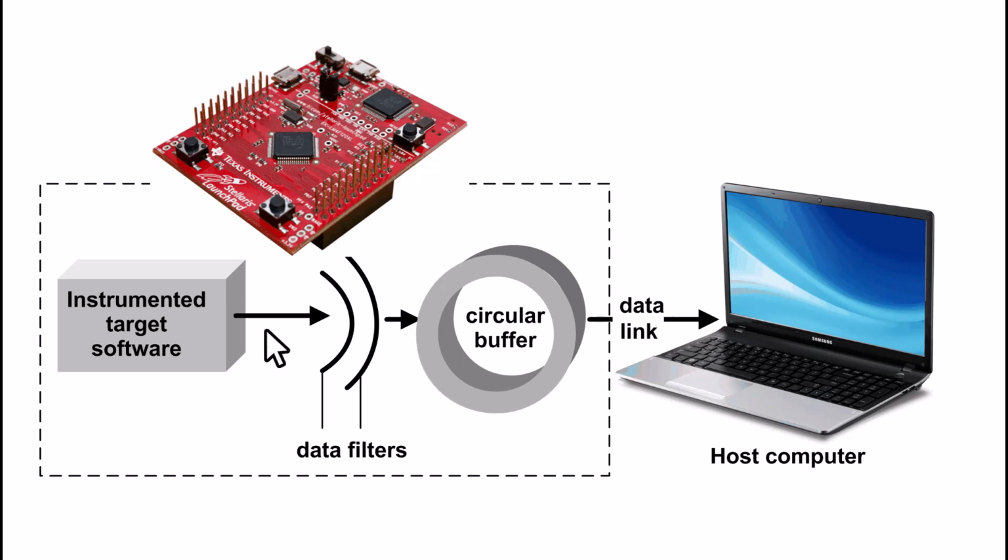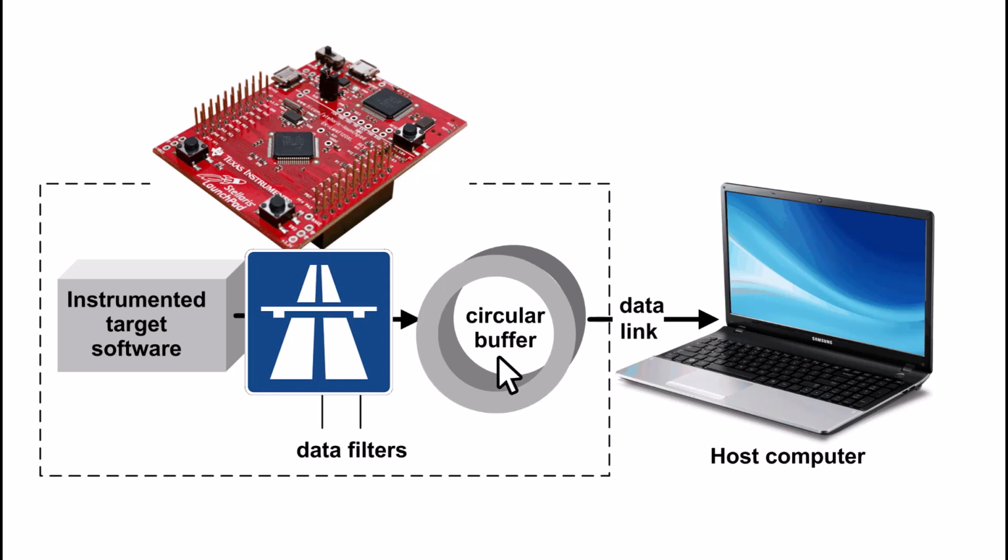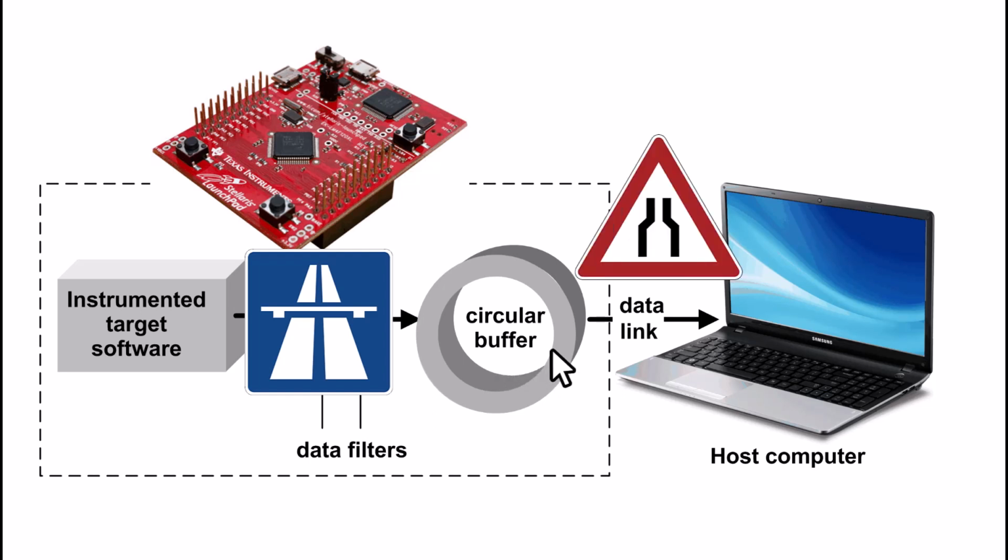The tracing information should be recorded quickly in native binary into a memory buffer inside the microcontroller. This takes only microseconds, which is important because it happens in the time-critical path through the code. On the other hand, the slow process of sending the tracing information to the host, which takes milliseconds, must be decoupled from recording the tracing data and occur when the CPU has nothing else to do.